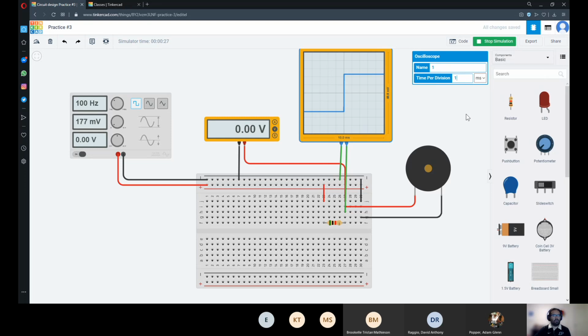So for example, it's a low frequency. Each cycle takes, in this case, 1 over the frequency. So the frequency is 100 hertz. That means there are going to be 100 cycles per second. So if I take 1 over 100, that tells me each cycle is 10 milliseconds. And that is exactly what I have here. So we can see here a full cycle of my signal.